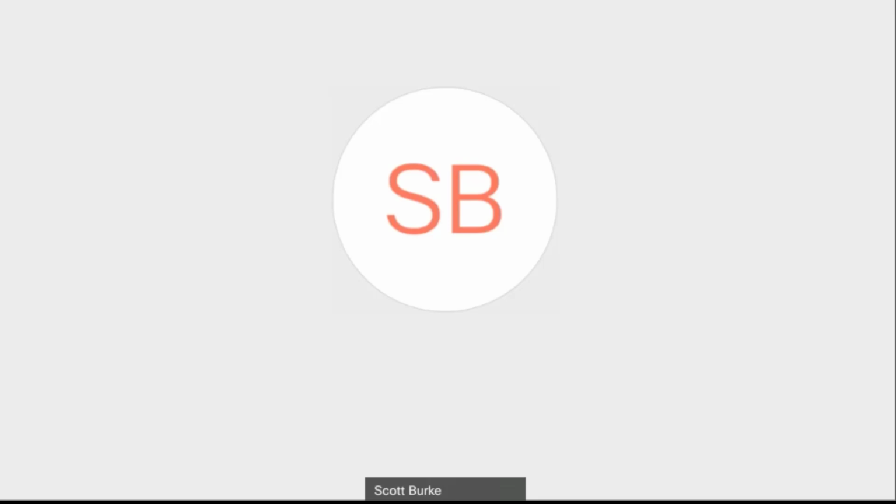All right, so are Revit uploaded files available for design work sharing? So basically, when you put a file up into BIM 360 Design, that is what that's for. You're allowed to have work sharing in there. You can have multiple people open the file. And if you give consultant access, the consultant also has a design license, free or trial. You can invite them into your project, give them a workspace, and they can upload and work on their file in the same environment like I showed, and you can link each other's files in.